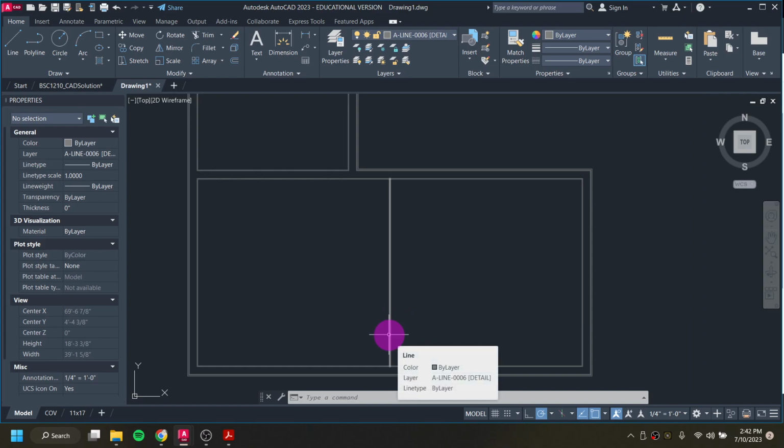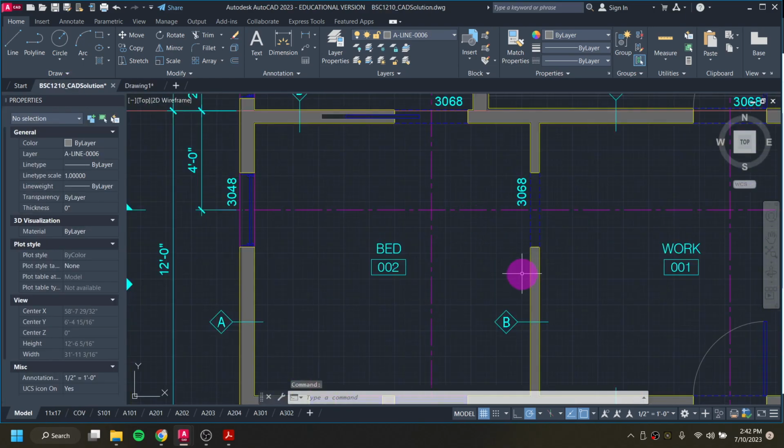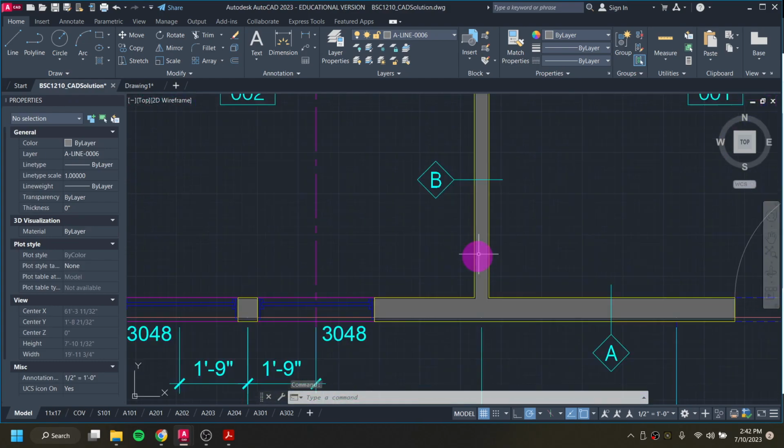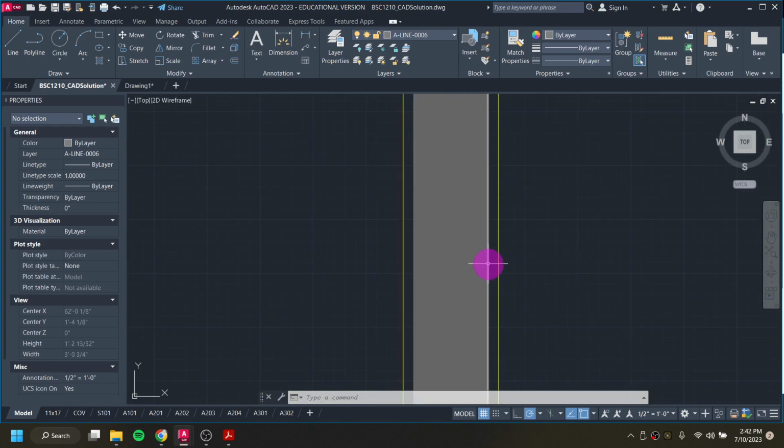Next, I'm going to offset this half of the distance of that 2x4 in either direction, because keep in mind this is the center of this stud wall. The center of it is that far away. And then I'm going to offset again out for the gypsum wallboard, out again for the gypsum wallboard. Since this interior wall is a 2x4, we need half of 3.5.